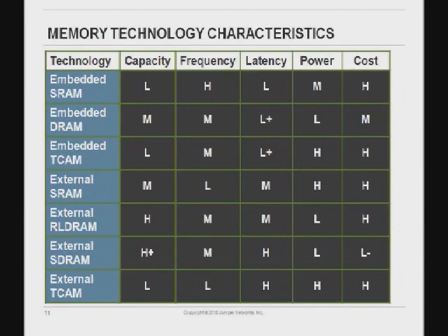But between different types of memories, we can see they are also different. The SRAMs, which stands for static RAM, are 6 transistor cell devices for each bit. They are higher performance and lower latency, but they are smaller and more power hungry than the DRAMs, which stand for dynamic memories.